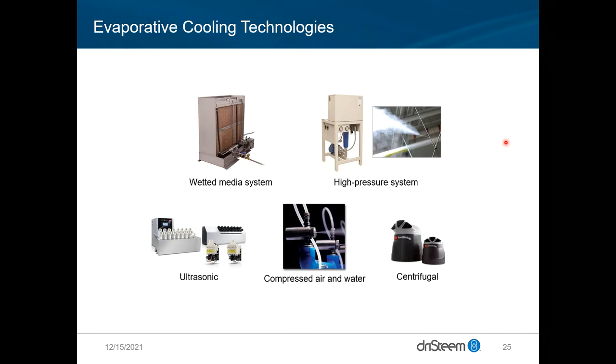Again, they do the same thing as far as humidify, but because the energy for absorbing that water is taken from the surrounding air, that is going to cool the air at the same time as it's humidifying. All the previous steam humidifiers do not change the temperature of the air very measurably. So that is important to keep in mind.